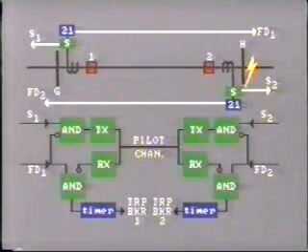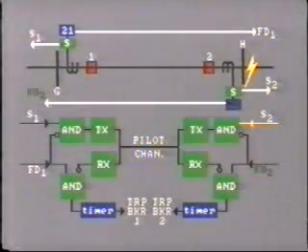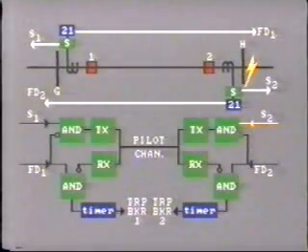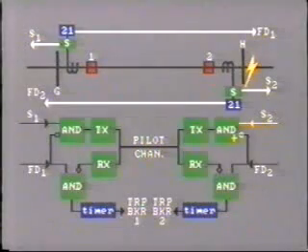Now, the logic diagram. When the external fault comes on, the starter relay at station H operates and sends a positive signal to the AND box. However, fault detector 2 has not operated, so it is not sending out a positive signal. Note on the diagram the 0 number at this input. Convention tells us that the logic circuit reverses the signal. That is, a 0 input signal reverses and becomes a positive signal.